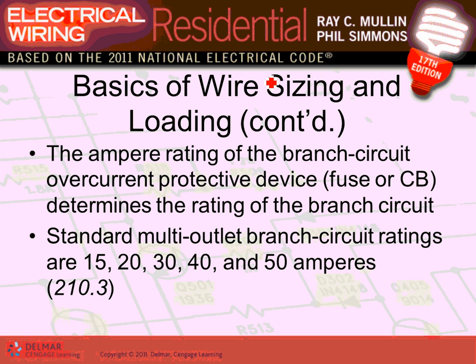Here's the concept that we just talked about. Right in here, I would exclude this one slightly from our project, but you can use it. The branch circuit by code can go 15, 20, 30, 40, all the way to 50 amps. For dwellings, like I said, these are the 3 circuits.